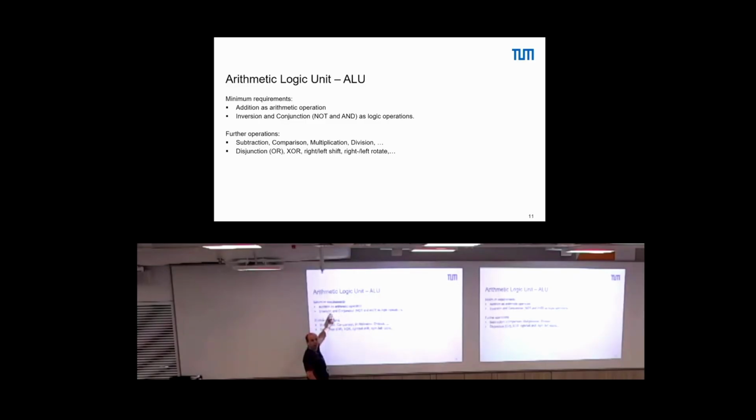Then with these few gates you can process effectively everything, whatever task you ever need. Because the rest is a mapping of that here, and you can just build, for instance, the XOR operation out of inversions and ANDs. You can build an addition out of a 1-bit addition and storage. You can build a subtraction just as an addition, and so on and so forth. So everything, whatever you want to compute, is covered by that.